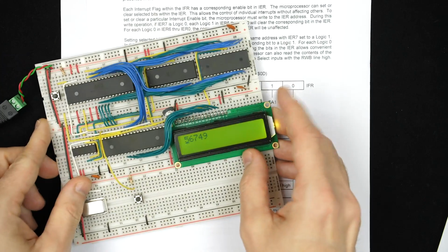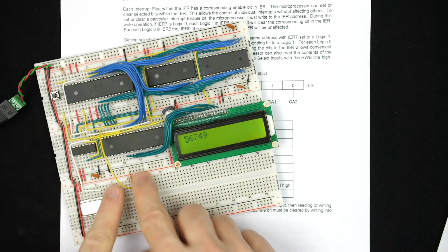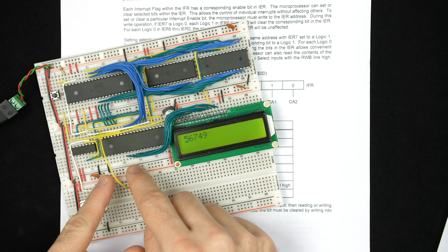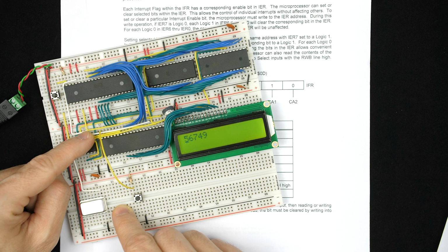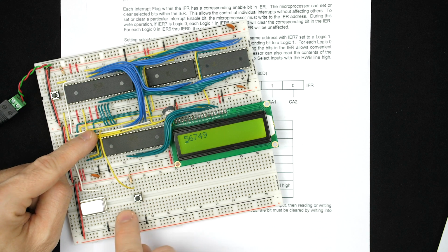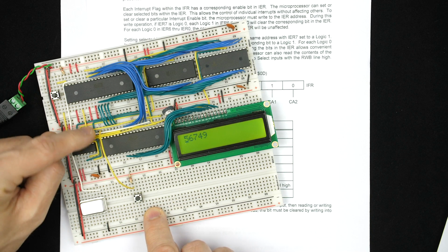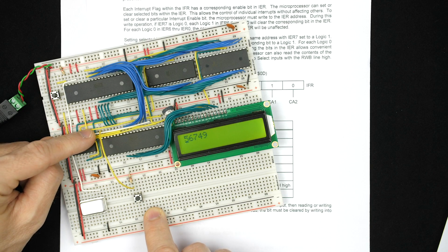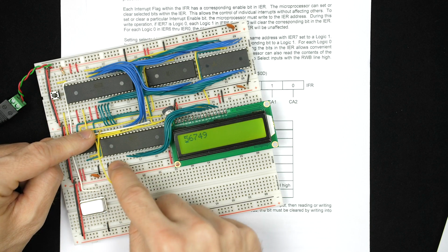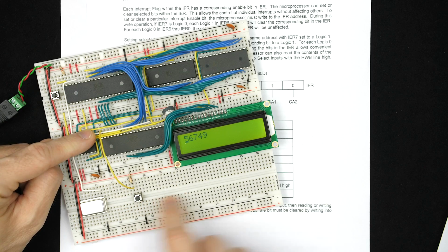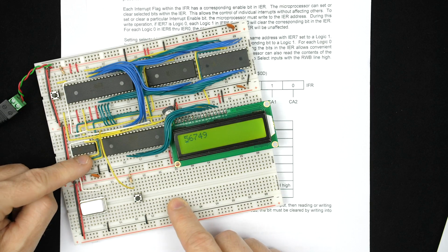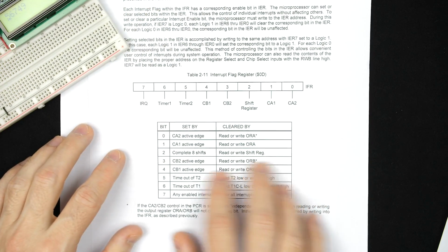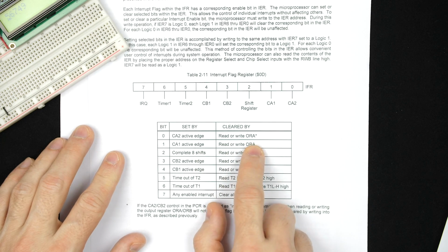And I think the idea there is that if you had 8 bits of data going into port A, you might have them ORed together and hooked into this pin here, so that if any of them changed, you would have some way of detecting that. So you could have a bunch of buttons, all ORed together and sent into this CA1 pin here. But then each individual button would go into a different bit of port A. And then when you press any of the buttons, it would trigger the interrupt. But then when you read port A, you could figure out which button was pressed. So I think that's why it's designed this way. But in any event, the thing you do to clear the interrupt is reading port A.